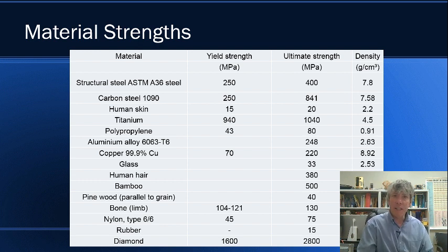But that should give you the idea that just because something's metal doesn't mean it's going to have the same properties, and you know this from your materials classes, but there's quite a variation. In fact, what was happening in that example was that the material was yielding. It was permanently deforming, right? Because they started out with the right shape, and as the material moved, it didn't completely move elastically. It moved plastically. So in other words, it got some permanent set in the spring. The springs changed their geometry.